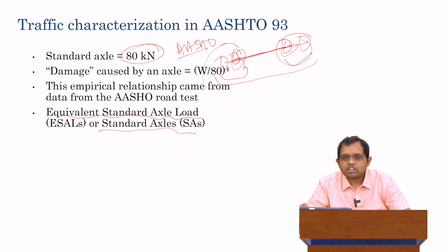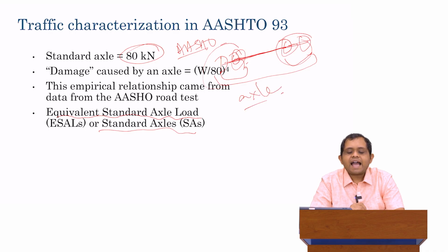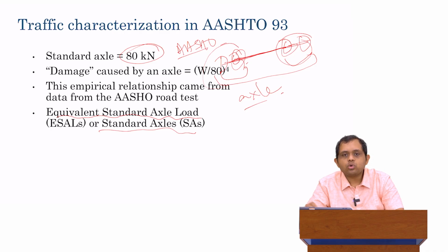So this entire construction, the tires which are connected by the shaft, this whole thing we call an axle. So when I say axle load, I mean the total load of the entire axle, which is distributed between the tires. We'll talk about distribution in a second. But when I say axle, I basically mean the total tires which are connected using this shaft. And when I say axle load, I mean the total weight which is being borne by this entire axle, which consists of multiple tires. So back in 1956, 1960, the most typical axle load was an 80 kilonewton axle load inside the US.